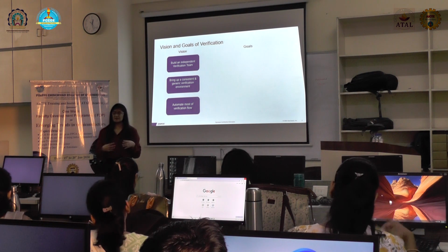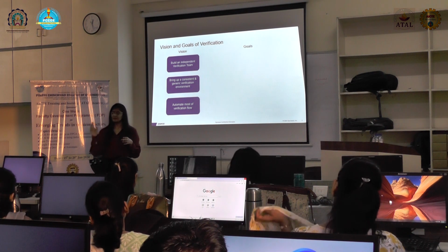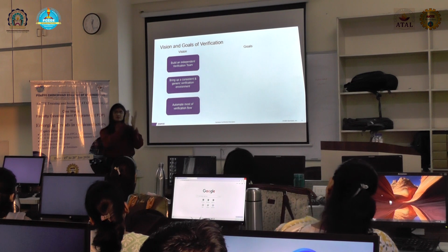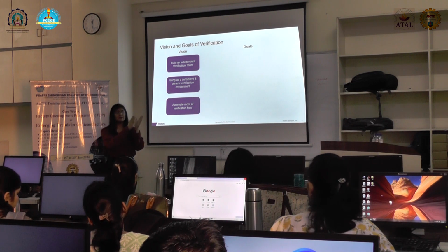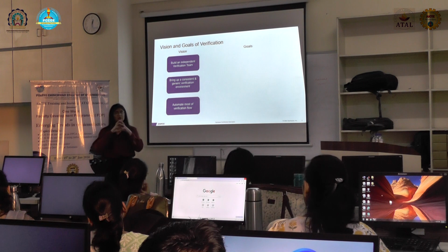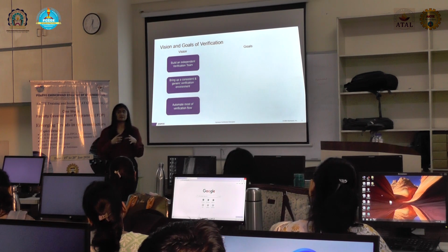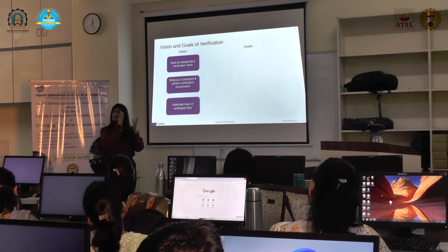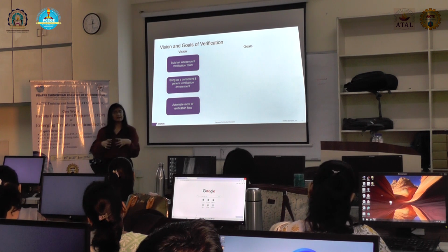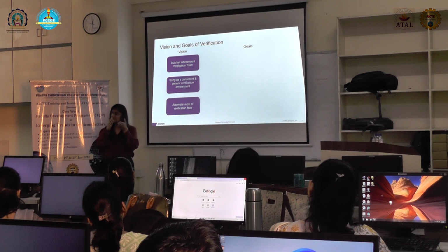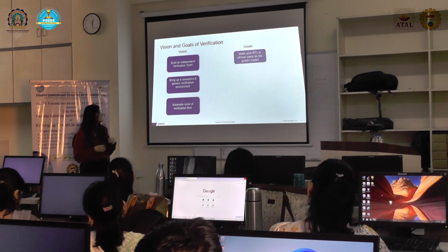Now what we have to do is randomization. When we run one test case, it's targeting a specific area only. We need to run that multiple times in order to cover the whole metrics that we have developed. So regression is nothing but repeating that particular test case multiple times, so that we can collect and merge the coverage that we have. So we collect the data in multiple runs in one go, and in that way we can have all the data that is required to complete the verification. So that is the regression.